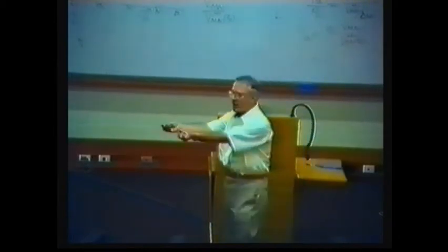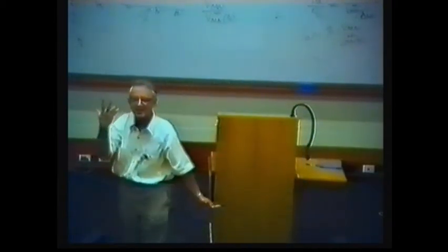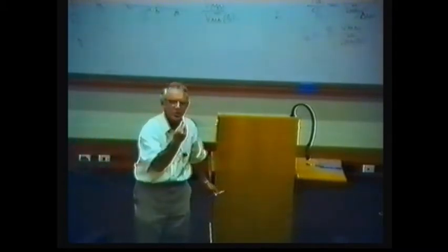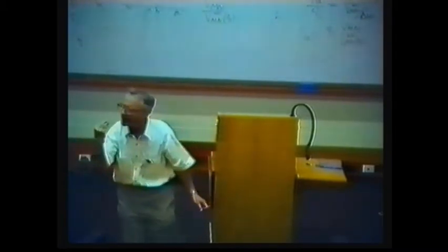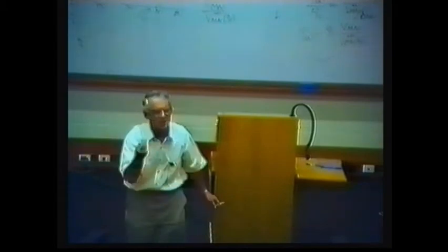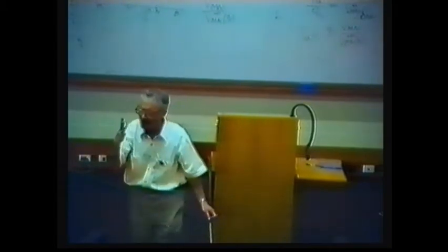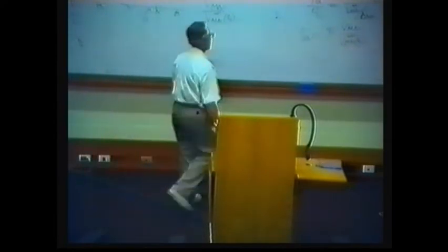But since before we didn't have computers, we had to work by hands, by eyes. So we greatly wanted curves which would reflect the geoelectrical section better than the field itself, the voltage. That was the reason why apparent resistivity was introduced.